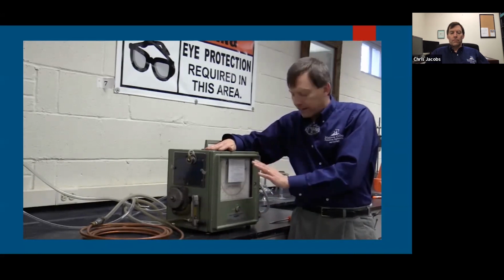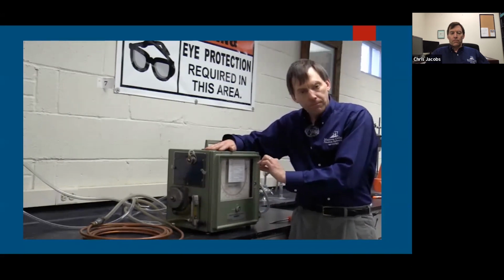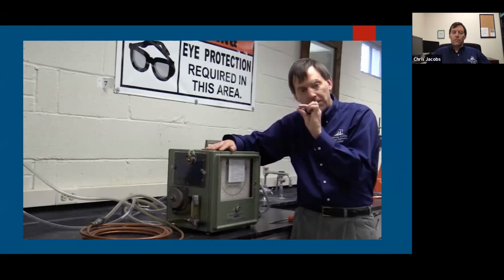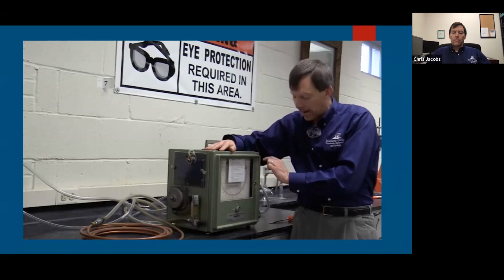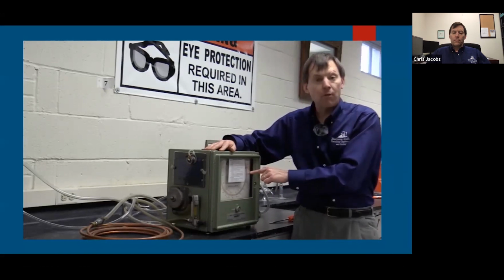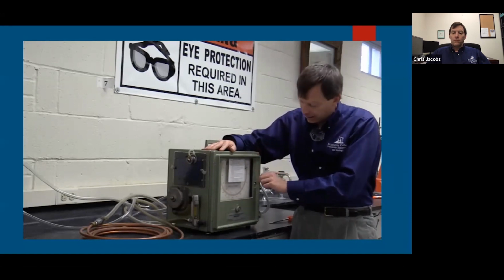One thing I will mention about the needle, this needle does not have a parallax mirror on it. So it's not like you can line it up exactly across like you would do with some of the meters where there's a parallax. So the parallax effect is not necessarily an issue. However, this needle has a very flat surface. So you can look at the needle cross and then you can read the specific gravity directly off of that. And if you look and see from the scale over here, we have 1.00 at this location and 0.9500. So each of the major indicators is 0.01. So you don't have to be exact with worrying about parallax in this case.